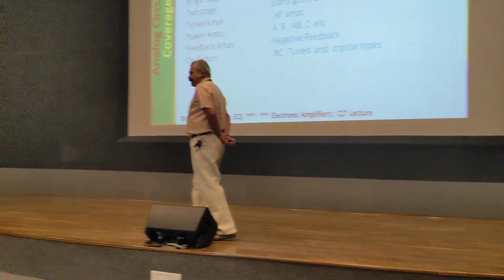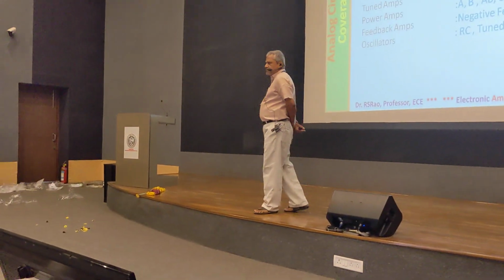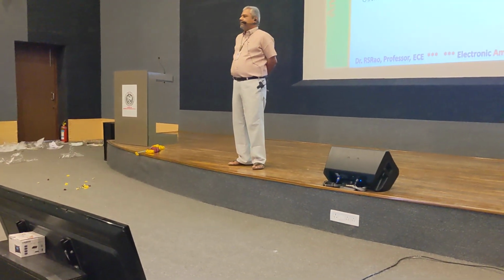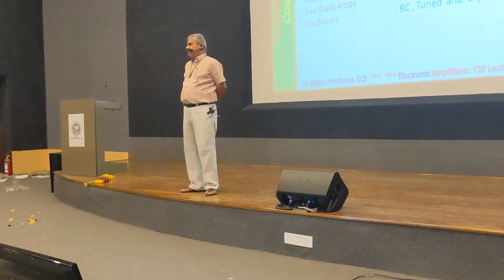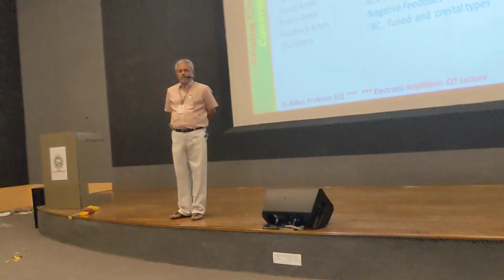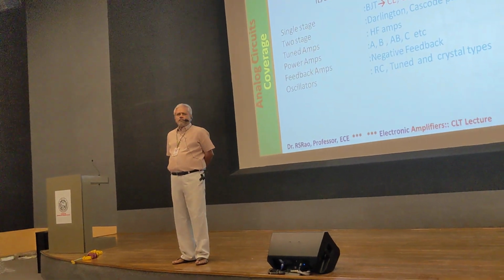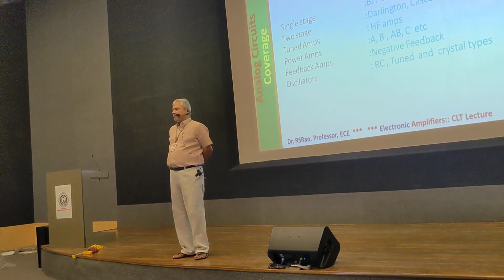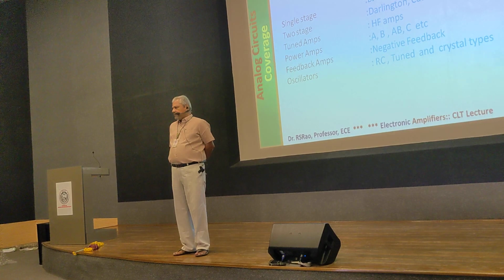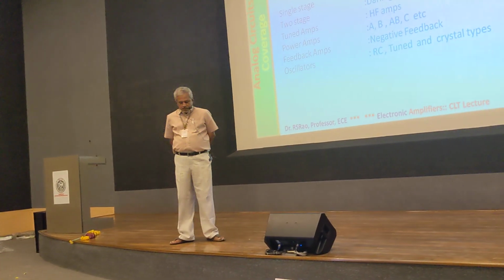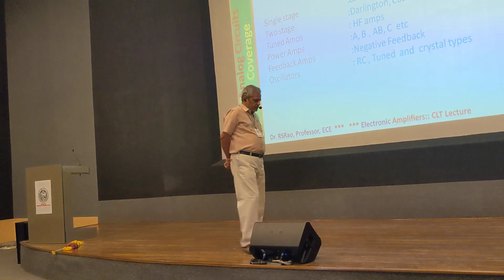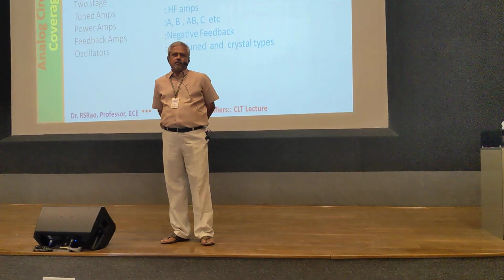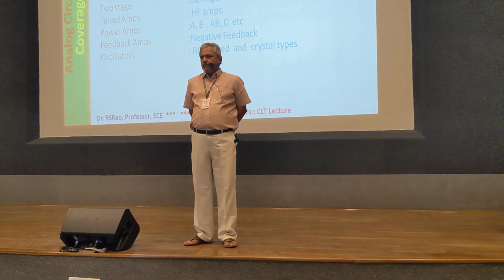Why are they called tuned amplifiers? An amplifier amplifies the signal, which makes the signal large. That's okay. Why are they called tuned amplifiers? The reason is the load of this amplifier is a tuned circuit. Most of the time it is a parallel LC circuit that is the load. So the use is on the receiver side of radio communication. The title tuned amplifier has come from the usage of a tuned circuit as the load in these amplifiers.